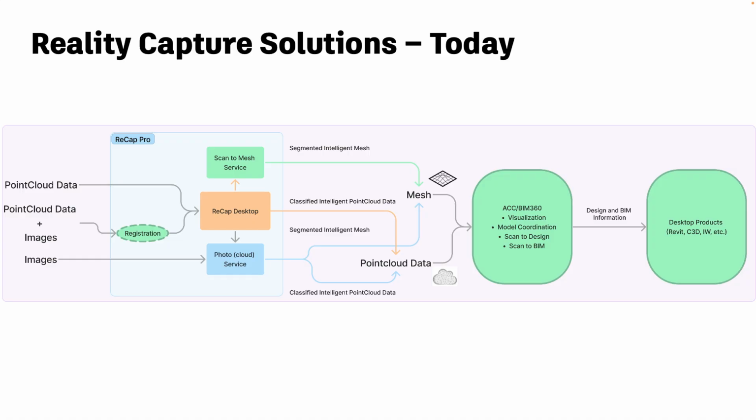You can overlay your point clouds or the mesh from point cloud on top of your Civil 3D model or the Revit model or the Navisworks model and so on. So without even downloading anything, without even getting too much into the project, you can actually visualize how it fits into my drawing, what is the work I need to do, how this existing condition helps me. You can check all those things just with a click of a button.